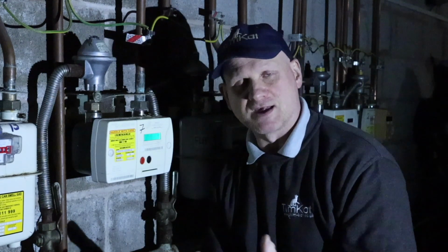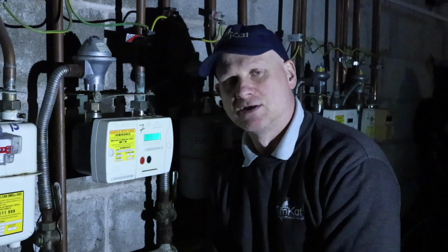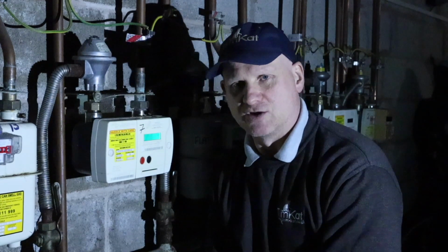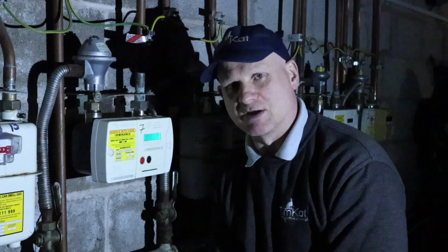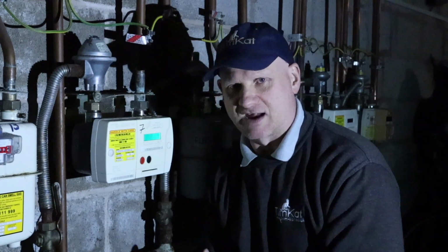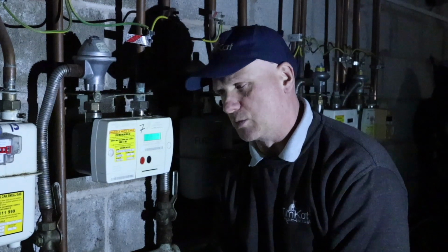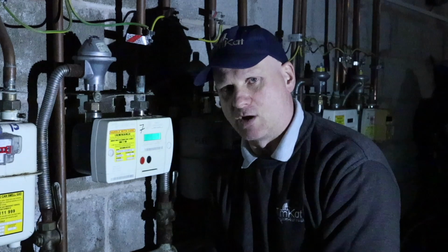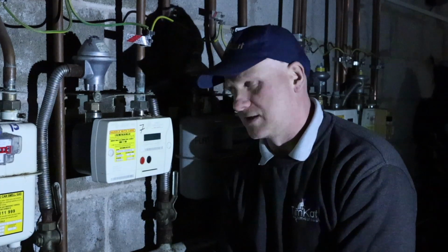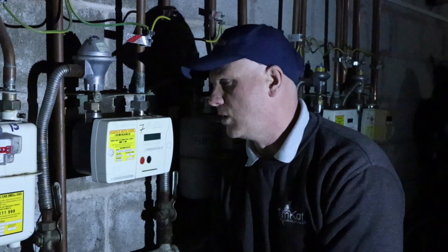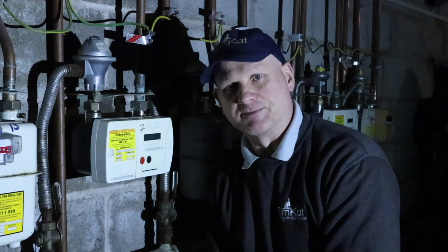And then we can take our first reading from our second, we can times by 30, give us meters cubed an hour. We can times it by the 38.7, the calorific value of gas, divide by the 3.6, divide by the 1.11, which will give us our kilowatts net. Okay, so that's how we do this meter.